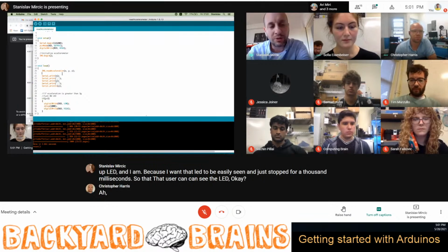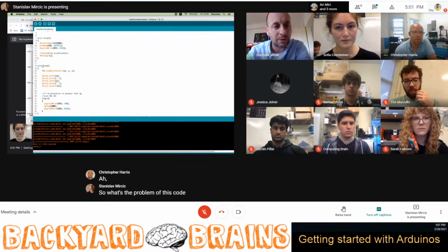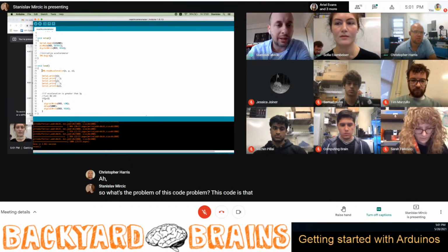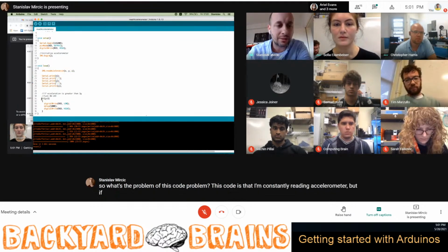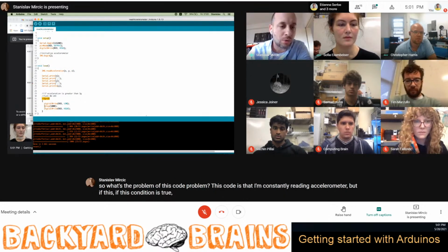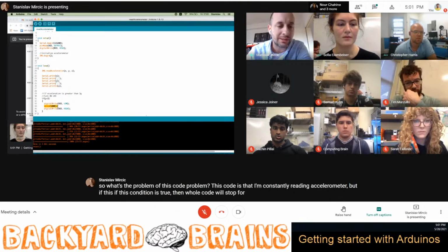Okay. So what's the problem of this code? The problem is that I'm constantly reading the accelerometer, but if this condition is true, then the whole code will stop for 1,000 milliseconds.